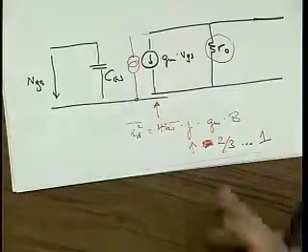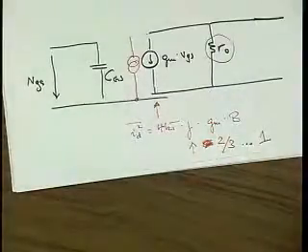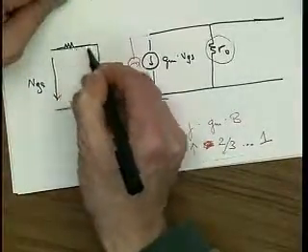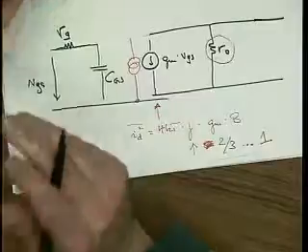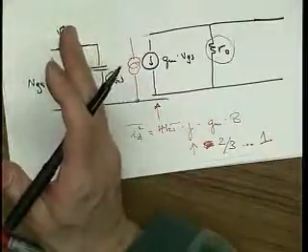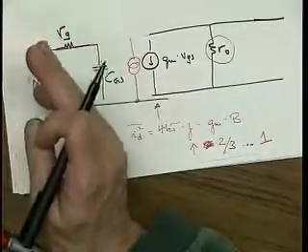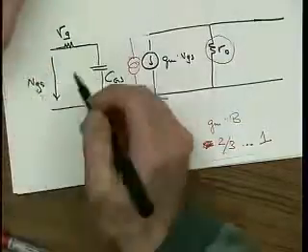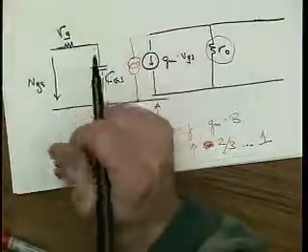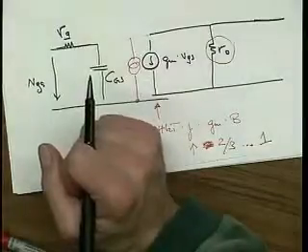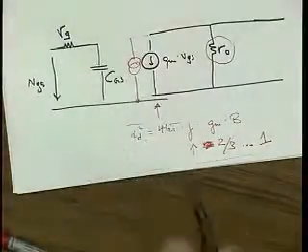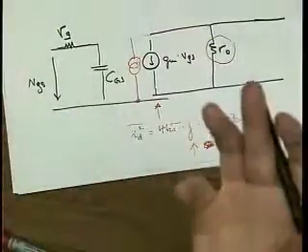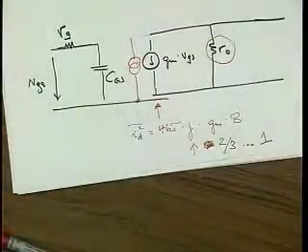And then the capacitor, we know it is not noisy, but what sometimes is an issue is, of course, the gate is poly. Maybe it's silicided, but nevertheless, it's going to be resistive. And especially in RF circuits, at the antenna impedance, maybe 50 ohms, or if you have a transformer, maybe even lower, and then we add here another 20 ohms or so, well, we get really significantly extra noise.